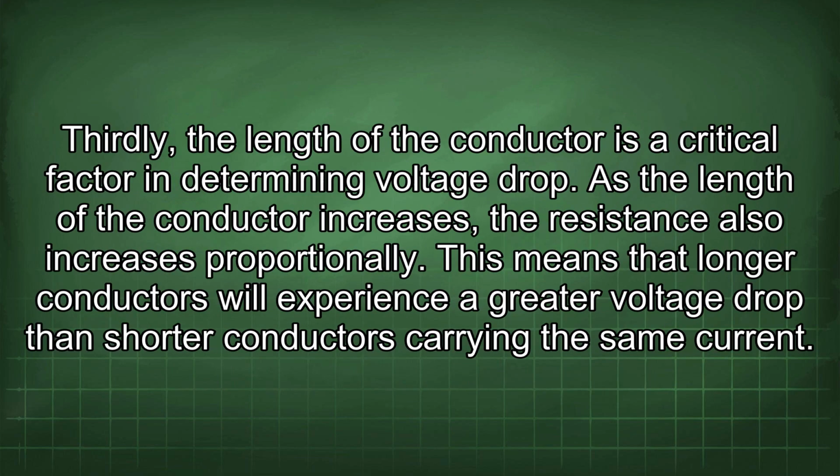Thirdly, the length of the conductor is a critical factor in determining voltage drop. As the length of the conductor increases, the resistance also increases proportionally. This means that longer conductors will experience a greater voltage drop than shorter conductors carrying the same current.